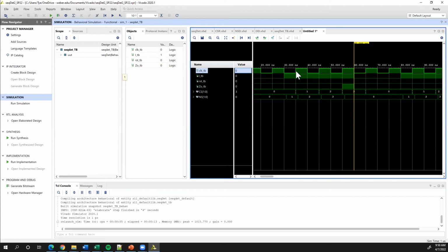And so let's go ahead and build a Moore state machine. But let's do it for something kind of different. Let's just go ahead and say, without doing all of this work, let's detect the sequence 110. Right, let's just change what we look for. And all we have to do that is think about what that means.